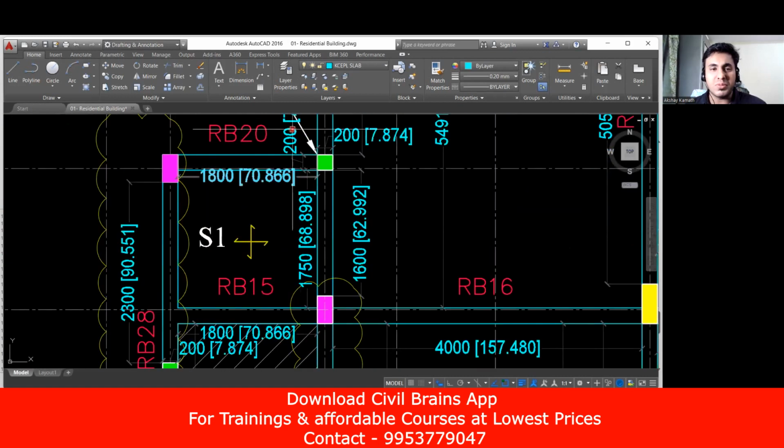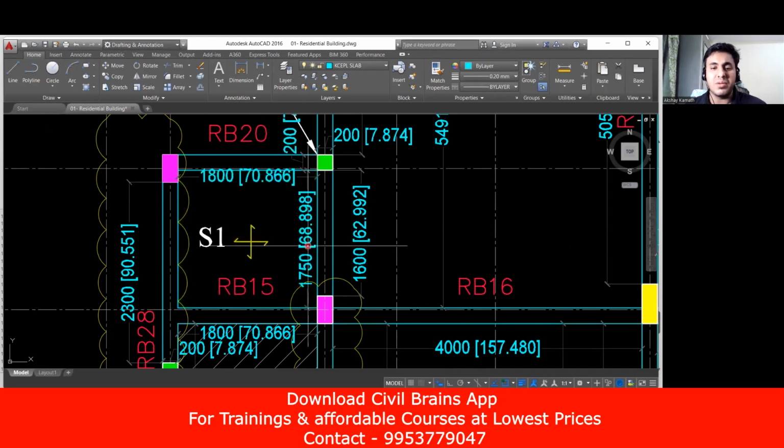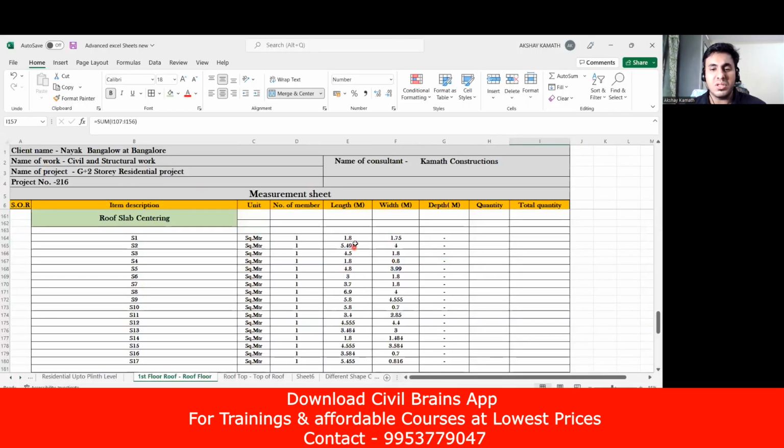So again, I want this much area. Agree with me? This is my slab centering quantity, outer of beam to outer. So what I'll do, I'll take AutoCAD. From AutoCAD, I'll measure this outer to this outer, which is 1800. And from this outer to this outer, I'll take, okay? Beam outer you have to take. So 1750. Remember how much it is? 1800 by 1750. Go to the Excel, you see 1800, 1.8 and 1.75.